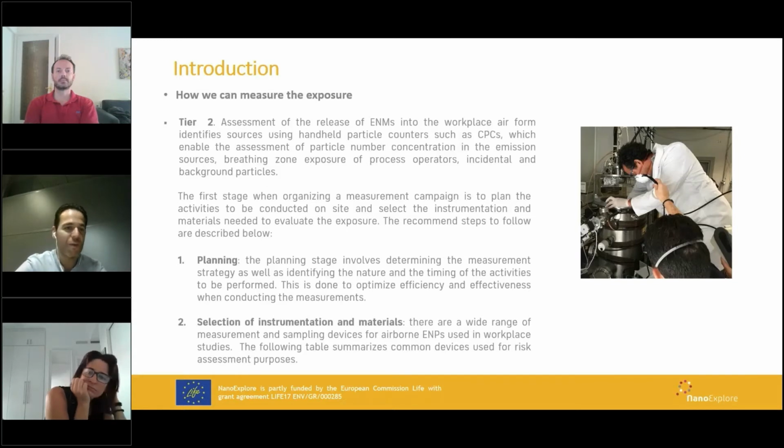After compiling this information, we can analyze all the data. And then if we understand that there is a potential release, we can visit the company. We normally use particle counters, simple CPCs, for example. There are some of them based on different technology, but normally we use these particle counters based on the condensation of materials. And normally we measure around the particle breathing zone. That's more or less 30 centimeters from the mouth. We normally use a tube if we are not allowed to go into the process,